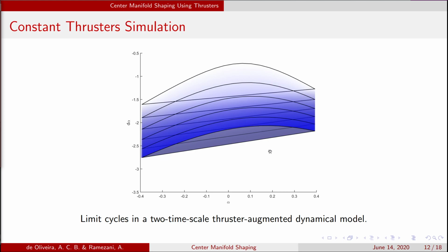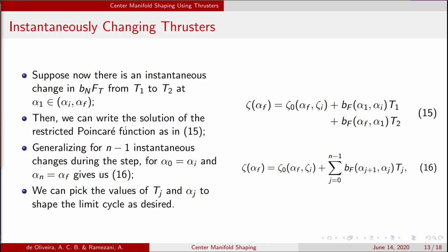They are very similar to the results from considering a second-order dynamics for the thrusters, except they are slightly farther apart since the instantaneous converge to the steady-state value. While the thrusters clearly flatten the limit cycle by changing its shape, this is somewhat limiting since, for example, the robot presents faster velocities at impact the more you shape the limit cycle, which might, for example, damage gearbox and motors. To circumvent this problem, we look at the instantaneous changes to the thruster magnitude during the step.